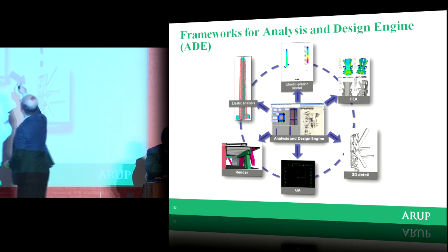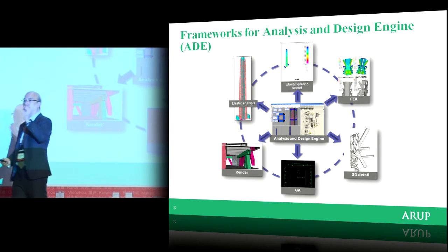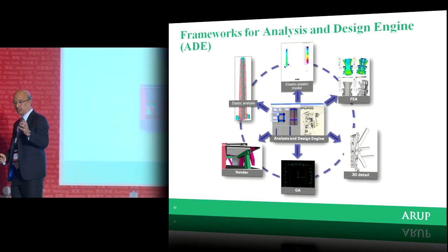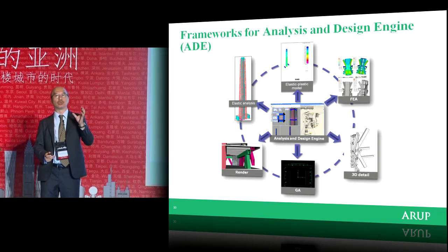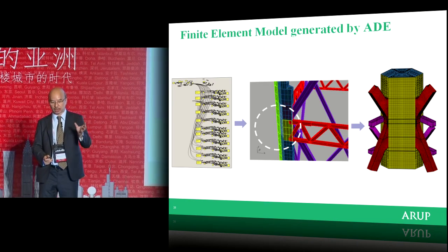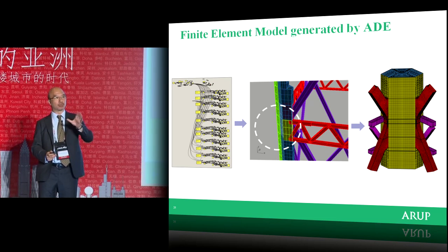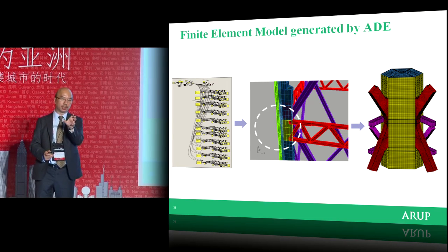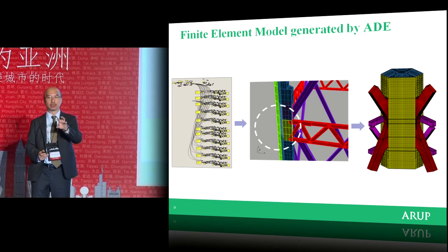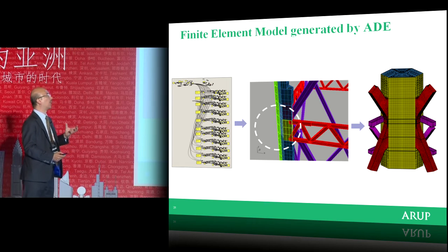And by that, we can export a connection IGES model, and then we can do meshing, and then do finite element analysis, and then get the result, right? So if the geometry changes again, the connection will change automatically, and then we can repeat this process, but with the finite element model ready in hand.